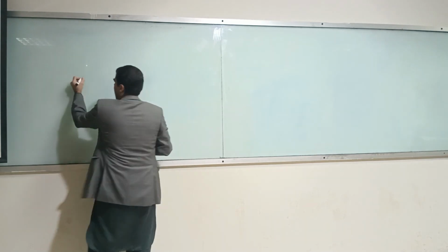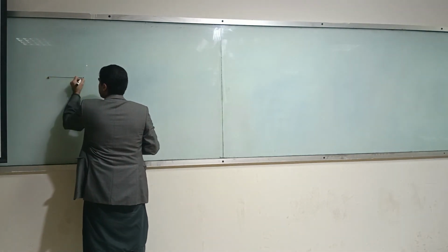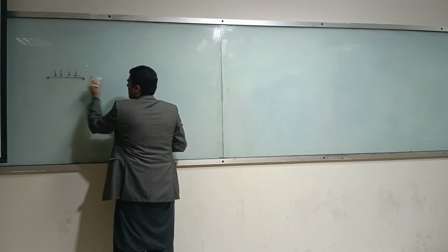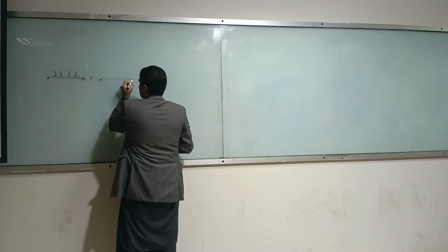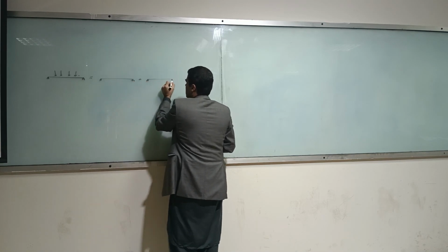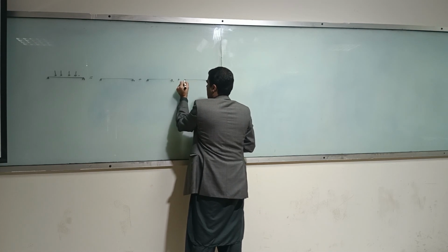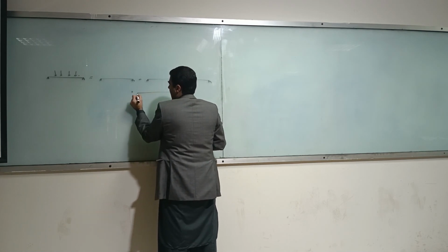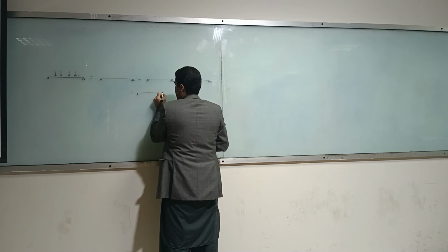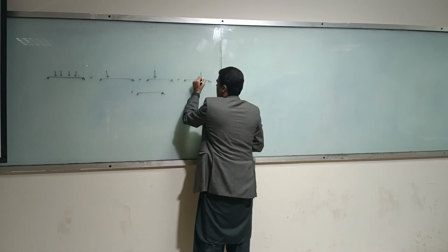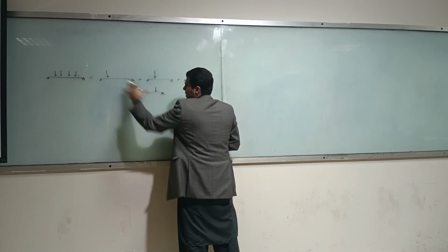So if I have a beam which is subject to many loads, I can have it divided into several beams of the same length and same supports, and I can have these loads applied independently.